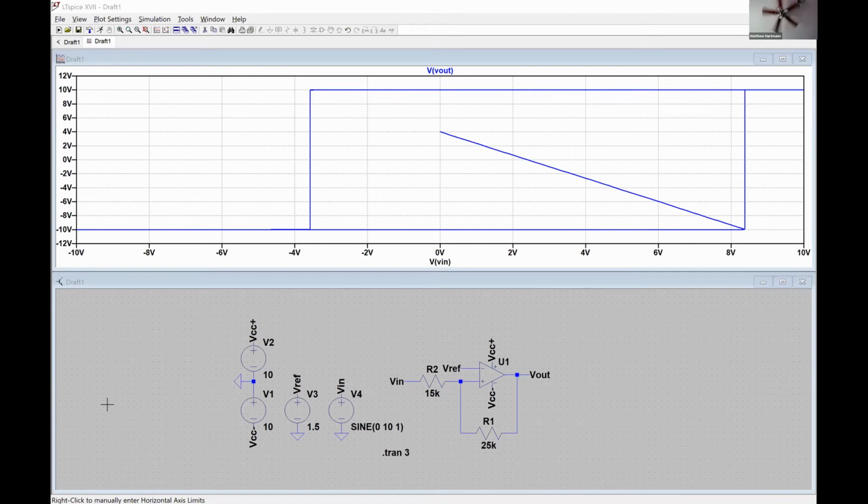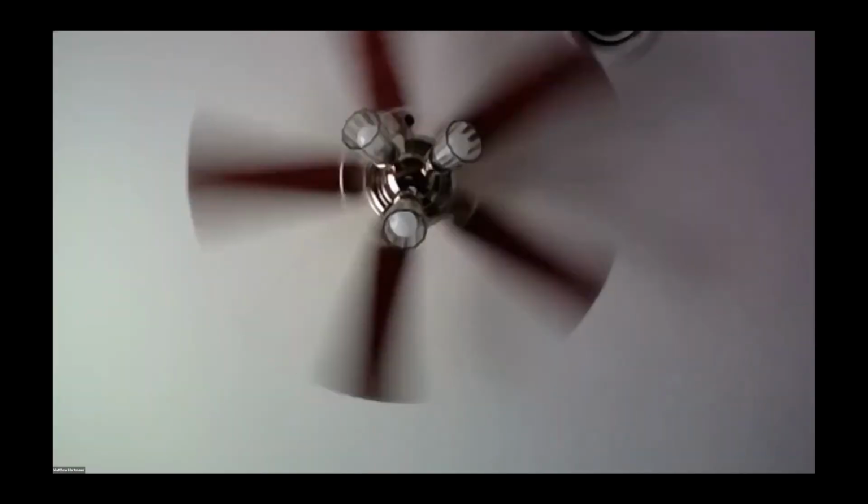So for problem 2, okay, so homework 2, which problem did you say? Homework 2, problem 2. Okay, so for homework 2, problem 2, what I would do is create a single op-amp, practical op-amp model circuit. So let me circle back to, this is one where using LT Spice probably isn't the best move, because your LT Spice model of your practical op-amp isn't going to be able to apply the saturation distortion correctly. So we're gonna have, let's see, something like this.